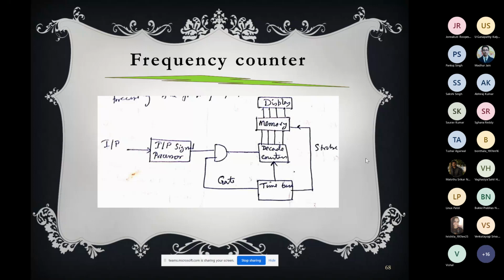that input signal to a square wave. That we can easily do with the help of a comparator circuit using an op amp. So with an op amp we can make a comparator circuit, and with the comparator circuit you make this input signal a square wave, and then you make a counter. With the help of the counter, you just count the number of latches, I mean when the square wave goes from low to high, and that count will be proportional to the time of the base signal.